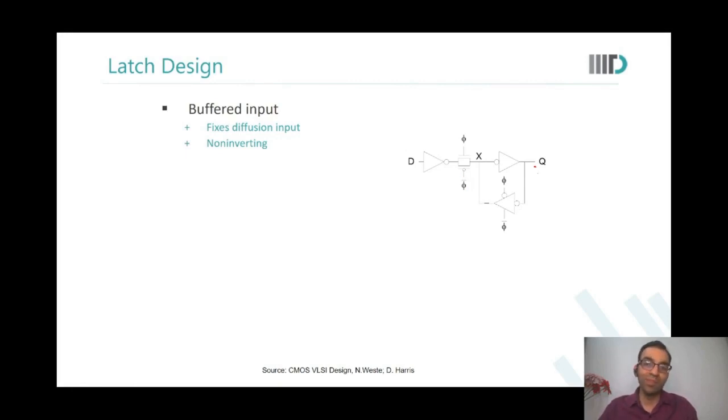So you tell me, what would you do as a designer? As a designer, sir, I think clock and clock bar should be independent to avoid that risk. But independent means, would you put two PLLs there? Sorry? Will you use two PLLs there, two clock generators there? No, sir. You will use the same clock generator. Okay. So if you have the same clock generator, then you have to generate CK and CK bar. Can they be exactly the same phase? No, sir. Can they be exactly 180 degrees apart? No, sir. There will be some inverter delay, right? Yes, sir.